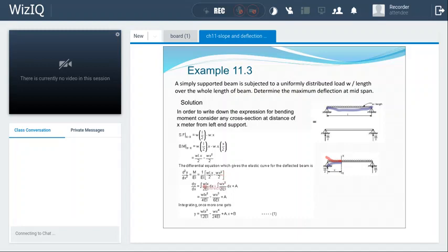So this is WL, x will become x square by 2. So this 2 and 2 will make it 4. WLx square by 4 EI minus Wx square. So again, you see when there is power 2, it will become cube, Wx cube over 3. So 3 into 2 will make it 6 in the denominator, plus this constant of integration. So WLx square over 4 EI minus Wx cube over 6 EI plus A.